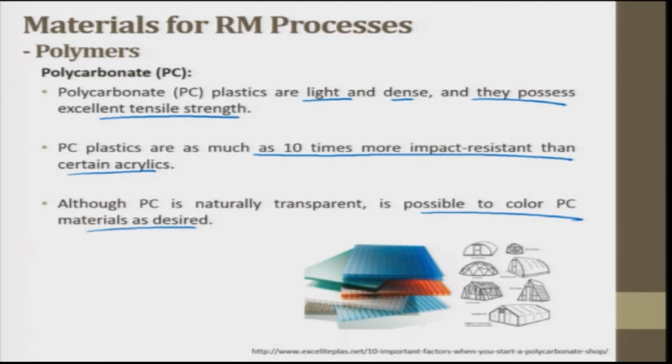Carbon reinforced polycarbonate plastics are strong and heat resistant enough to use in manufacturing intake manifolds and other parts subject to high temperatures. Now polycarbonates are relative newcomers to additive manufacturing, and it is also necessary to maintain high nozzle temperatures here. Again the temperatures of the nozzle should be from 260 to 300 degrees centigrade. This is nozzle temperature.